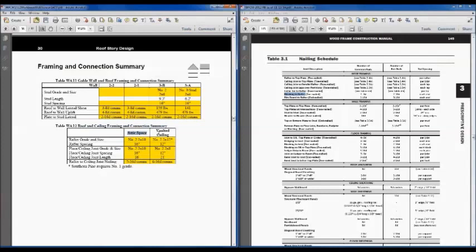and it would probably be pretty silly to do a 2x10 in one span and a 2x12 in the other. So rafters will probably not necessarily be used. You'd probably use a truss system. But again, this is an example problem, and so it gives us a way to show you some of those differences, especially how you see a difference between just a normal attic space requiring a number 2 2x10 and a vaulted ceiling requiring a number 2 2x12 at 12 inches on center. And then some of the other requirements as well. So that's a good summary table to show you some of those differences. And I'm going to stop there and ask Michelle to join me and see what other questions we might answer here for part 1.